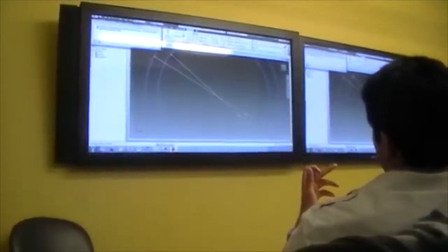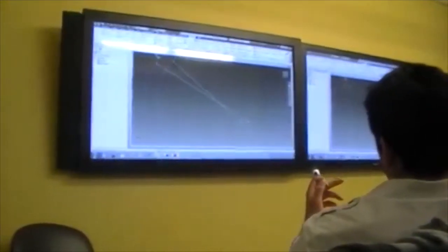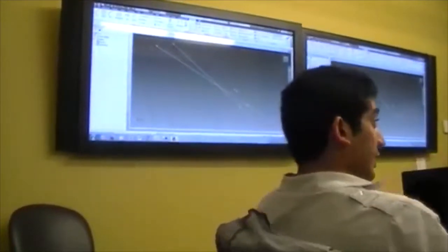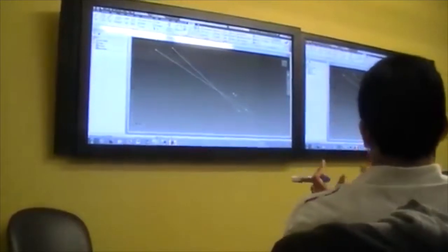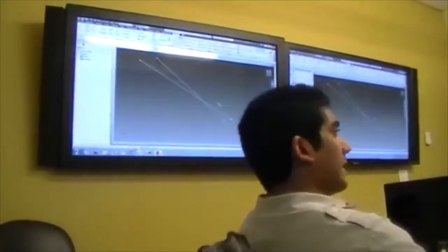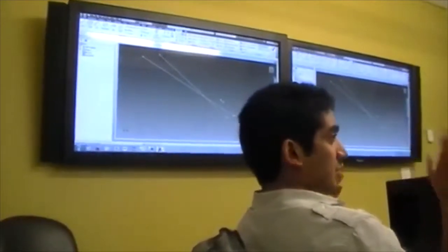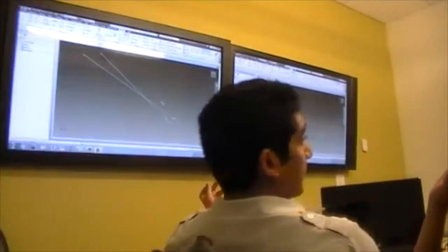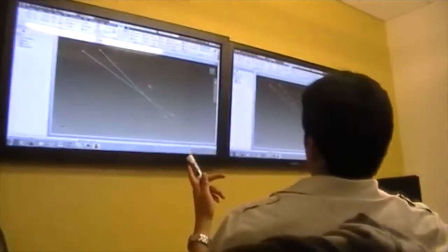But basically what that does is if I drew two circles that weren't sharing a center point, it would force them to share a center point regardless of where I move things. So that's a good way to make sure that your circles are actually lined up. And this comes more into play when you're using several different types of circles within one geometry. For example, a planetary gear system, you'd want to do something like that.